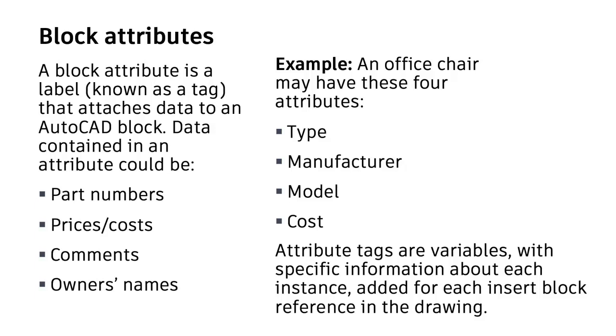AutoCAD also allows you to create tool palettes that link to your blocks to make it easier to access and use the desired block content. If you use a tool palette to access your blocks, it's important to understand that the palette is linked to those external block files as well. If those files are moved or deleted, the block tools on the palette will no longer work.